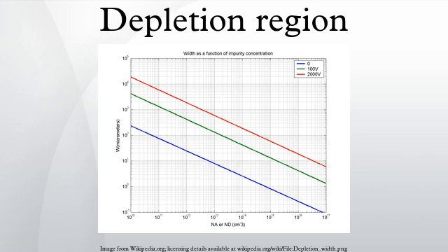the relationship. If the depletion width becomes wide enough, then electrons appear in a very thin layer at the semiconductor oxide interface, called an inversion layer because they are oppositely charged to the holes that prevail in a P-type material. When an inversion layer forms, the depletion width ceases to expand with increase in gate charge Q. In this case, neutrality is achieved by attracting more electrons into the inversion layer. In the MOSFET, this inversion layer is referred to as the channel.